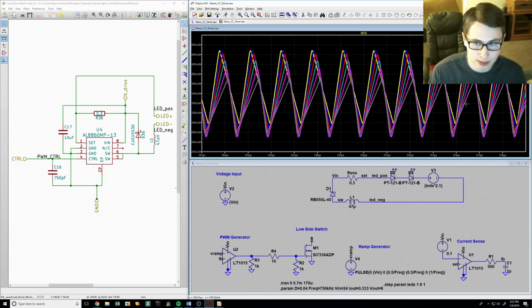2,600%. By a rough calculation with cursors, I determined that the steady state value was varying by approximately 30 milliamps. That's the RMS value, not the peak-to-peak value, or about 9%. Considering how much the output power difference is varying, that's pretty small.